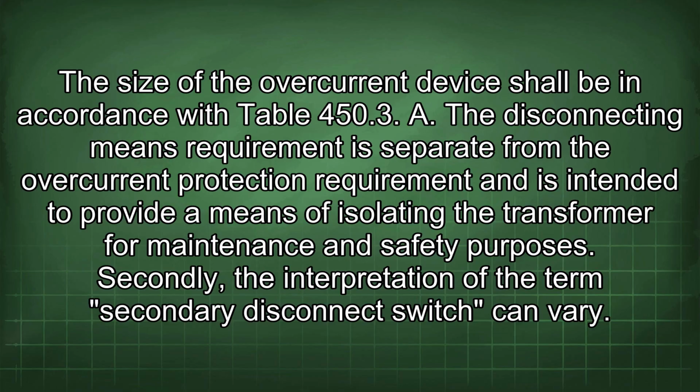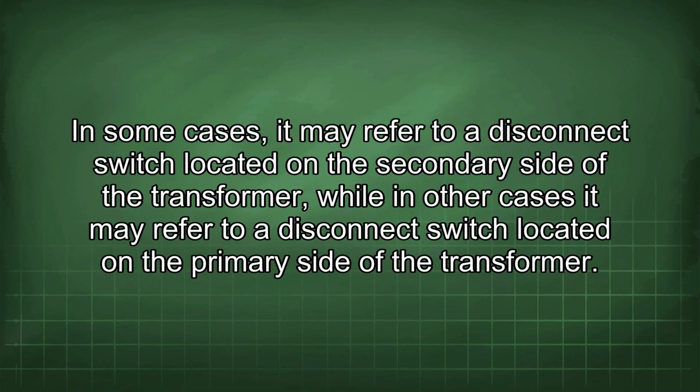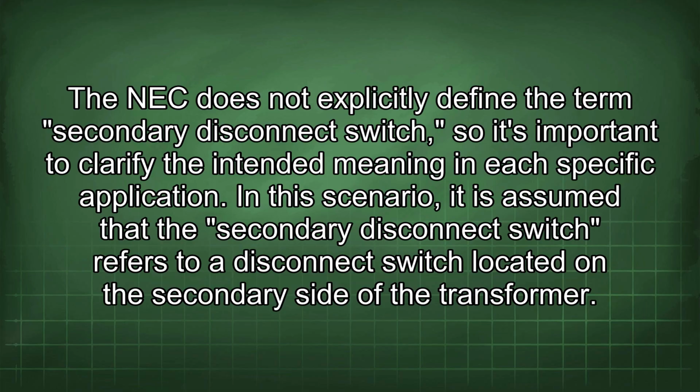Secondly, the interpretation of the term secondary disconnect switch can vary. In some cases, it may refer to a disconnect switch located on the secondary side of the transformer, while in other cases it may refer to a disconnect switch located on the primary side of the transformer. The NEC does not explicitly define the term secondary disconnect switch, so it's important to clarify the intended meaning in